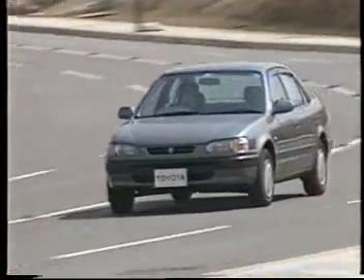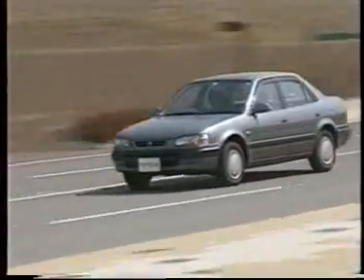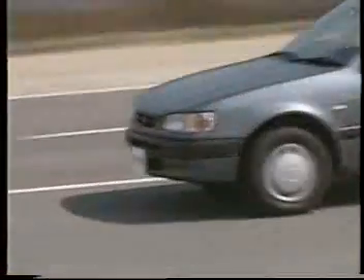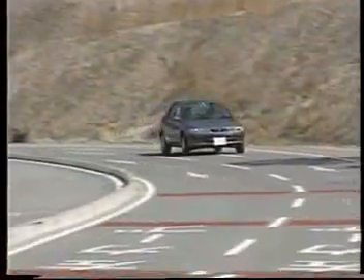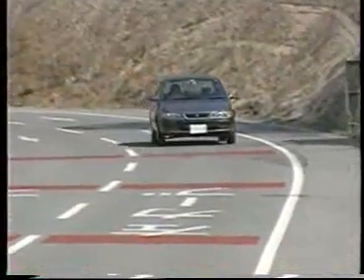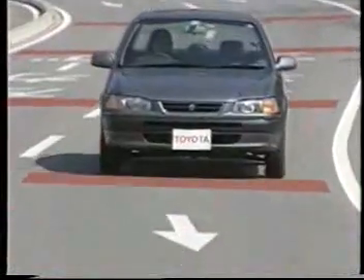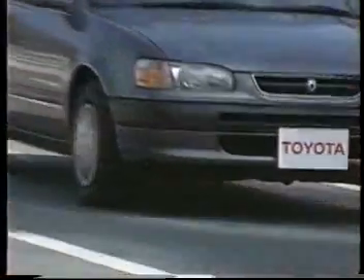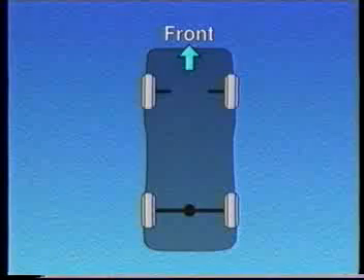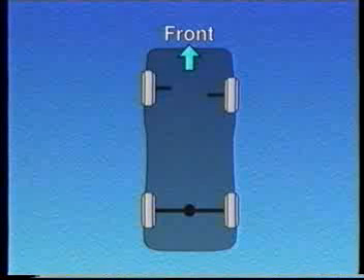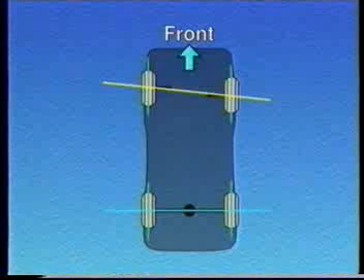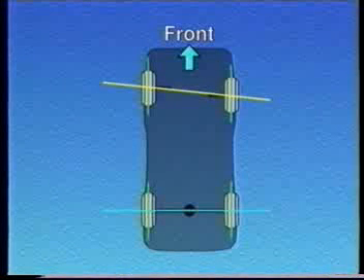Usually, the term wheel alignment is used to refer mainly to the alignment of the front wheels. However, total four-wheel alignment, including rear-wheel alignment, has become important because of the recent increasing demand for more sophisticated driving performance. For example, even if the alignment for each of the four wheels is normal, straight-ahead stability will be reduced when the front and rear axles are not parallel.